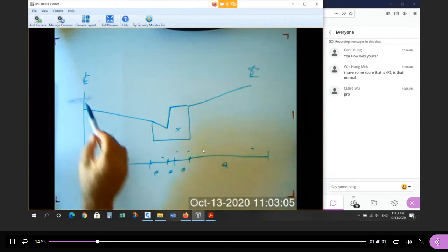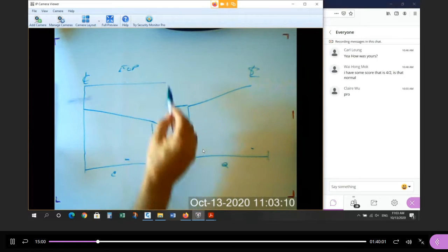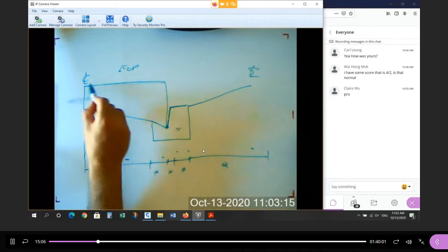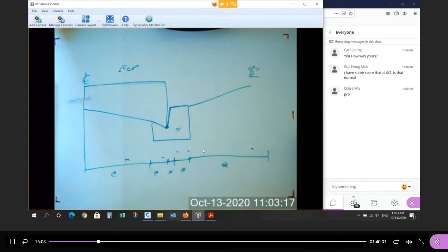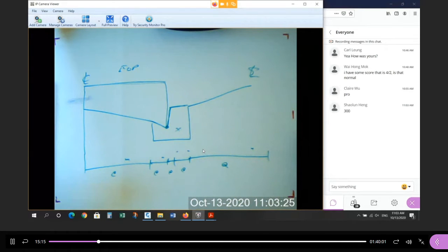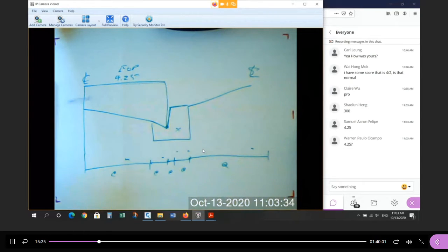So if we remember some of the dimensions, from the center line when we offset to what I've called the edge of pavement, this point here, what's this width? Anybody remember? Here's your offset from center to edge of pavement, which is the gutter line. What was this dimension? 4.25, that's right, because the edge of pavement dimension was 8.5, so half of that, 4.25, okay?